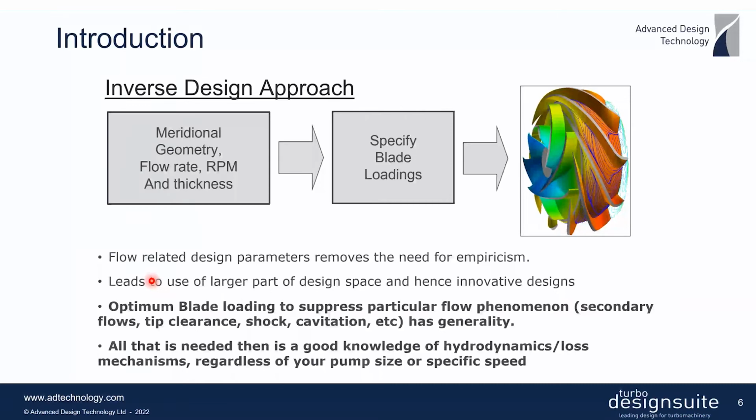Let's start with an introduction to the idea behind the inverse design approach, which we use throughout this presentation. As you can see in this workflow, these are the inputs that are used by the inverse design method to give us the final blade design. Apart from some basic parameters, these blade loading inputs are really flow related.